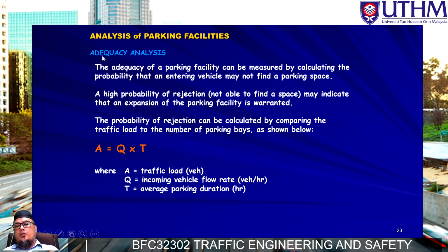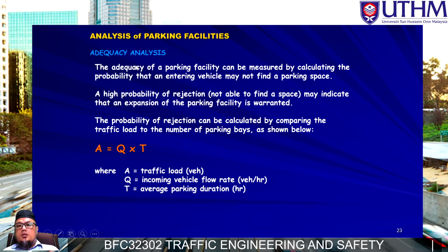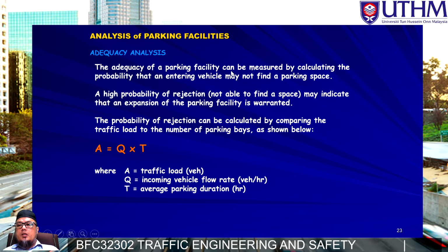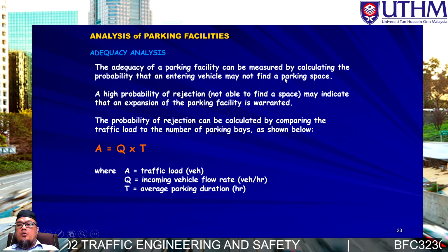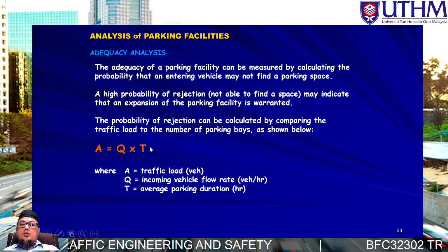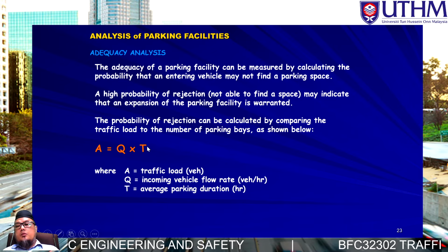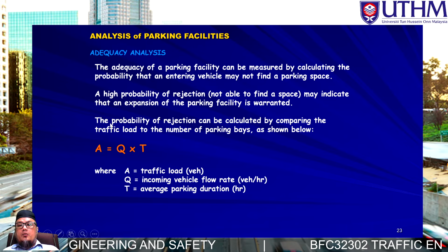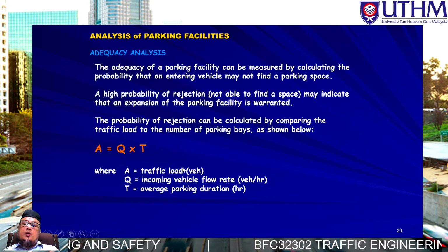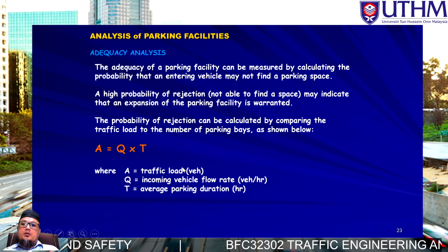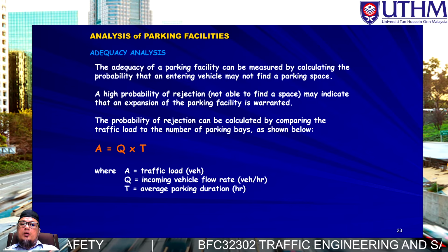Okay, analysis for parking facilities. First one, we look in terms of adequacy analysis. Adequacy analysis can be measured by calculating the probability that an entering vehicle may not find a parking space. For this method we just use a probability method. We want to calculate the probability of rejection. Then we know that the parking service is worthwhile or adequate or not.